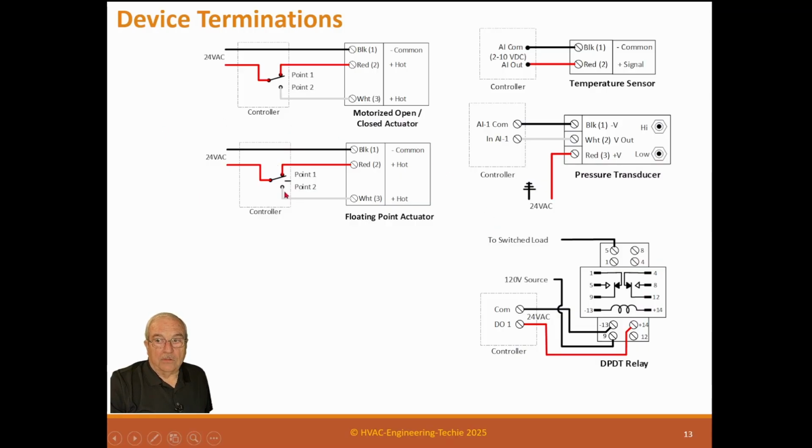Or if it needs to close, then it closes this point. Now it'll drive it closed. So this valve is either open or closed, not anywhere in between. This one here is like a modulator, but not quite. It opens, stops, waits, opens or closes, stops, waits. So it mimics modulation, but it is not modulation.